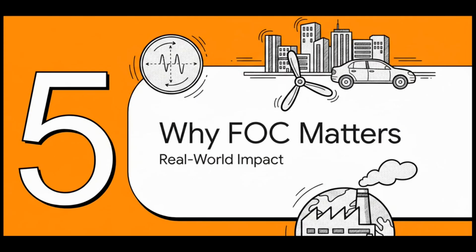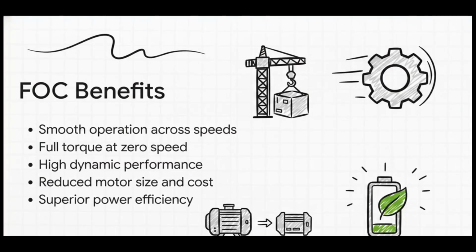Section 5. Why FOC matters today. Let's move on and see how all this microscopic math translates into massive macroscopic real-world payoffs. FOC essentially guarantees ridiculously smooth operation across the entire speed range. You completely lose that jerky, inefficient behavior of older control methods. Plus, with closed-loop IFOC, you can generate full torque at 0 speed. Think about a crane holding a massive payload completely still in midair. That's FOC at work. And because the torque is decoupled, you unlock this jaw-dropping dynamic performance for lightning-fast acceleration and